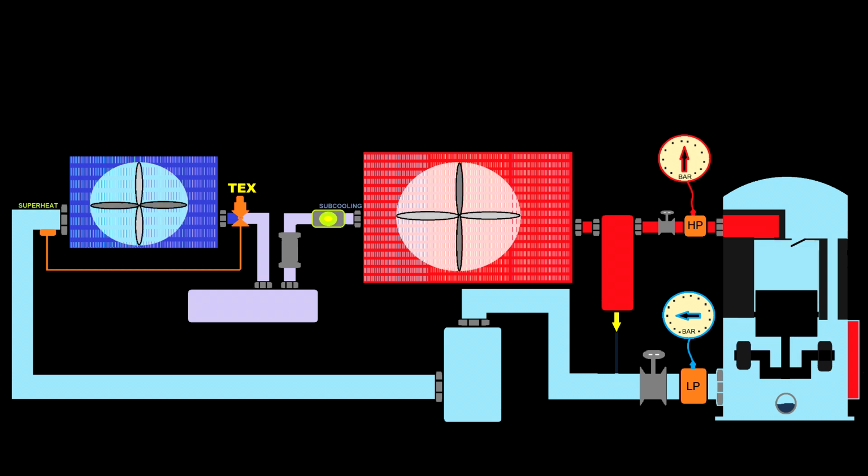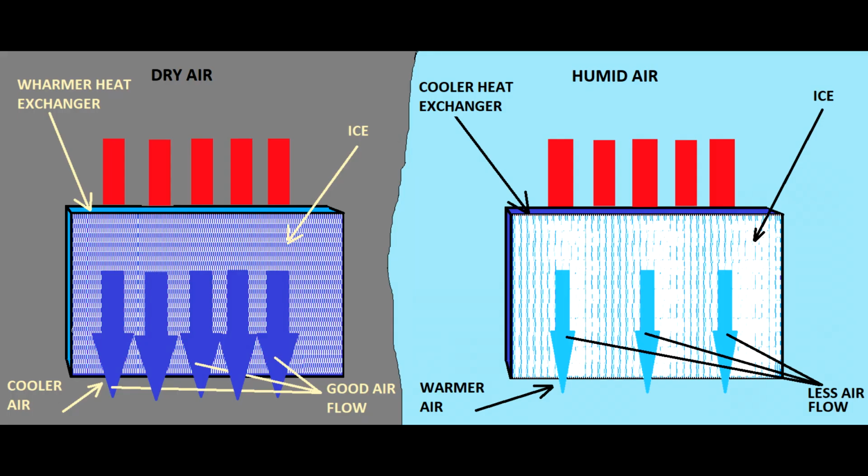If you look here, onto the discharge you have a high pressure, onto the return you have a low pressure. That's the ratio which allows you to create the refrigeration process. You really have to be careful with this ratio. You have to check what refrigerant you are using, and you have to apply the correct pressure difference between discharge and suction. Many refrigeration engineers are enjoying that they are creating cold, but the system on many occasions doesn't perform more than 60 to 70%.